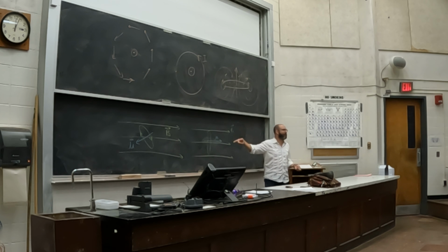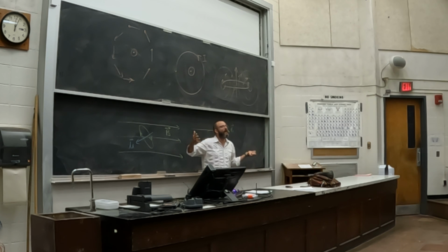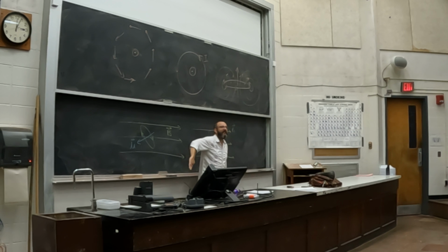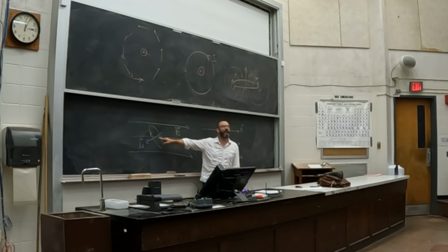The way this is handled usually in DC motors is to turn off this current halfway through the cycle. So see, where does the torque flip direction? It's right here, right? Right in this position, the torque is making this thing rotate here. But once I get past this point, the torque is acting oppositely, right? My angle has flipped, therefore the sign of my torque is flipped. So maybe a strategy would be to turn off the current here, which means that there is no magnetic moment